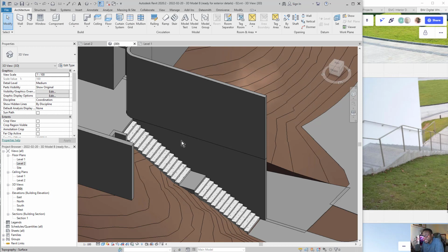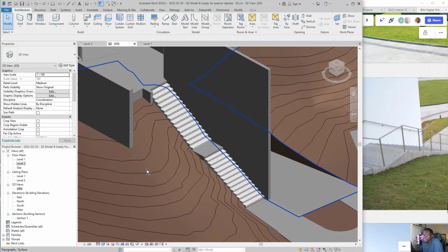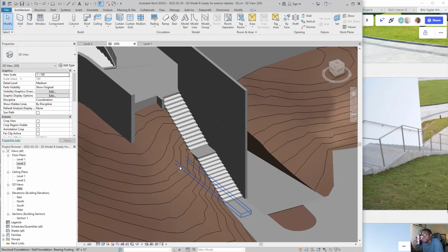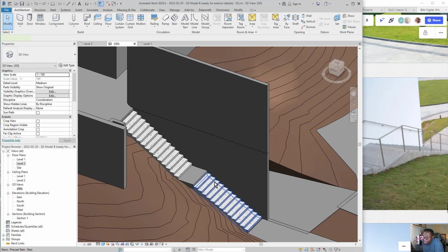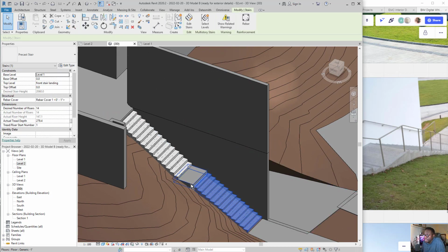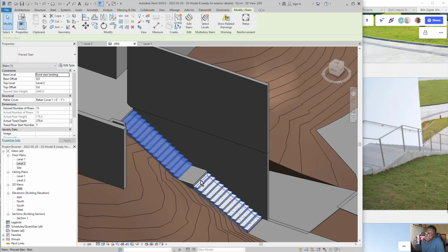Now if I just remove those railings, I want to highlight an important point here that might give some person some trouble. Now if you notice these stairs here, how I've drawn these stairs is that I've drawn a stairs here, and I've drawn a floor and then another flight upstairs. Now this can work, however this is not the recommended way to do the stairs. You want to try to do one flight of stairs in cases where you need to have railings.